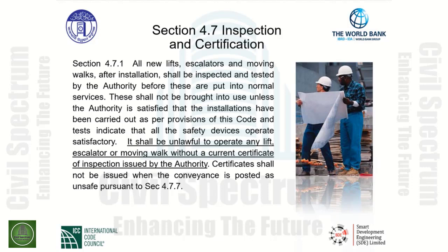4.7.1 indicates that all new lifts, escalators, and moving walks, after installation, shall be inspected and tested by the authority before these are put into normal services. This is very important, this part of the code, due to the fact that these lifts, escalators, and moving walks transport people to different areas of the buildings.